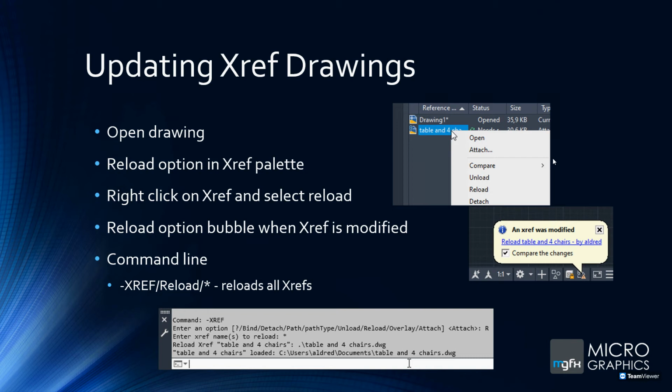I mean, if you're doing, say, for instance, some ducting, and someone else is doing the column placement in a building, all of a sudden you see the column placement shift. Now, it might go through your ducting, so you need to rethink where the ducting needs to go.